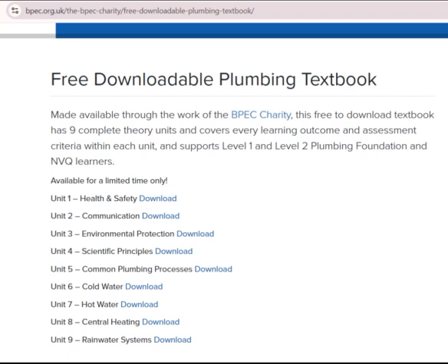Protection of central heating systems is a combination of the following: system flushing to remove residues, adding corrosion inhibitors and scale preventers, and the use of magnetic filters. These 3 points, together with regular servicing and maintenance, will protect the system and ensure its continued efficient service throughout its life.